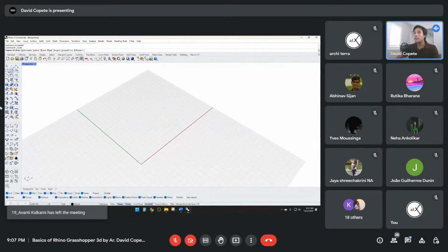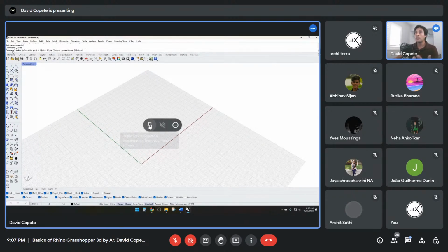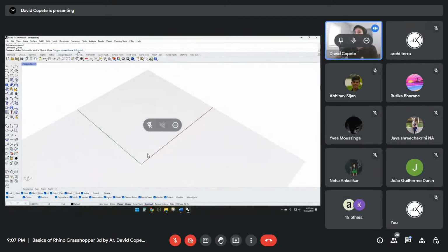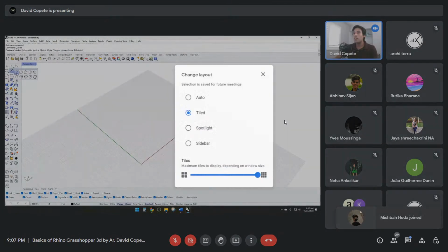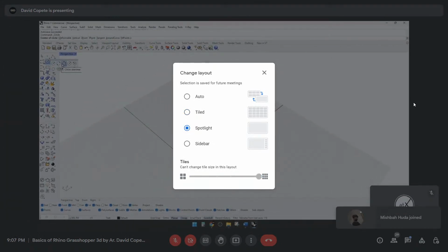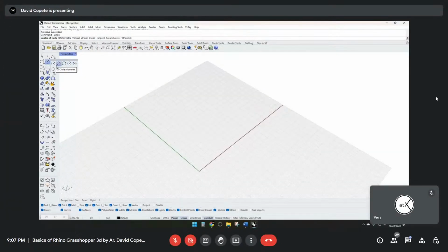Then when we click on the circle, notice that we have more options. We have the location, the center of the circle, and we have different ways of creating circles. In the same way that when we click down here on the icon, we have circle from center, 2 points, 3 points, and all of these different ways. We'll be just going over creating a basic circle. So the first thing we do is click on the icon. Second thing is create the center of the circle.